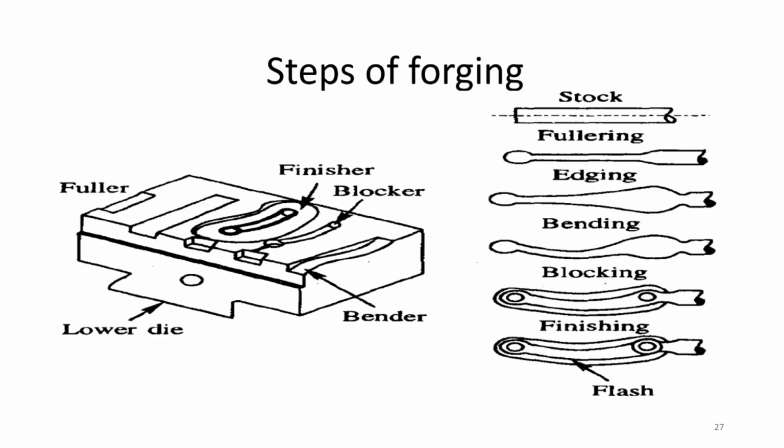Some nitrided steels, carburized steels: it's changing with the case depth. If the case depth is increasing, then carburized steels have higher hardness compared to the nitrided steel, and at lower case depth, some nitrided steels have higher hardness compared to carburized.